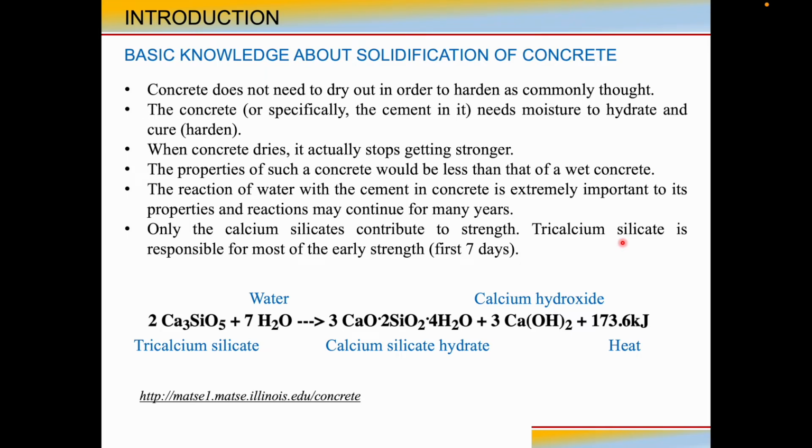Before going into the paper, first I would like to review what we studied in our bachelor degree. Here is the basic knowledge about solidification of concrete. Concrete does not need to dry out in order to harden, as commonly thought. The concrete needs moisture to hydrate and cure. When concrete dries, it actually stops getting stronger, which means the properties of dry concrete would be less than those of wet concrete.